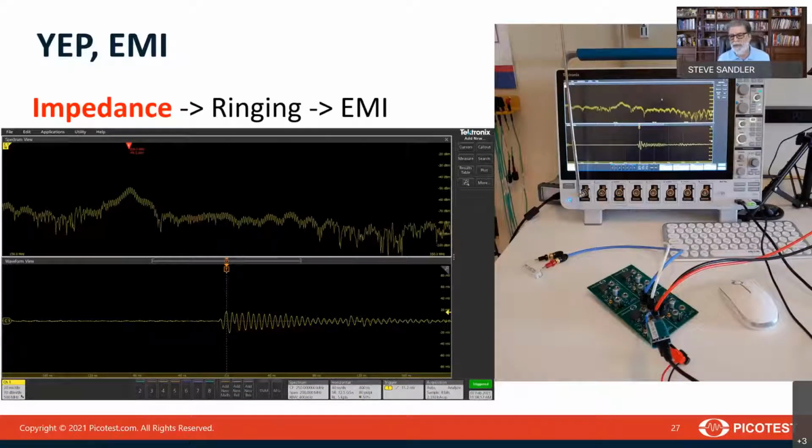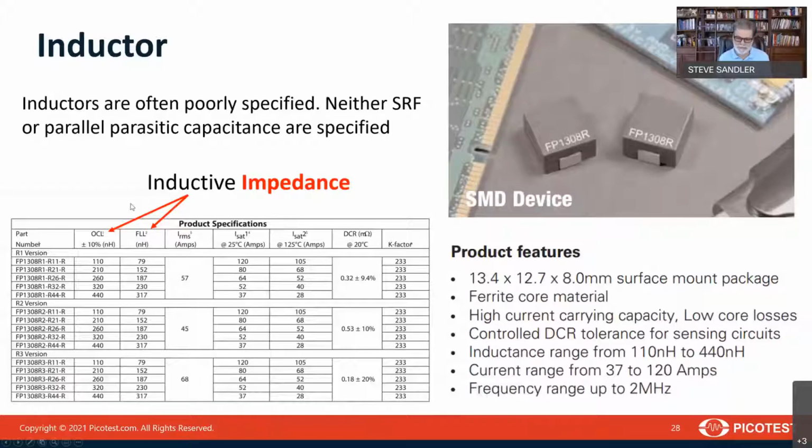And here we can see that, just looking at EMI, and I didn't even use a near field antenna. You can see I just put a telescopic antenna on my oscilloscope so I can measure the noise in somewhat far field to see what it is that comes out of this power supply. And sure enough, you can see there is that leading edge ringing frequency, and it shows up nice and clearly. So that's how that converts.